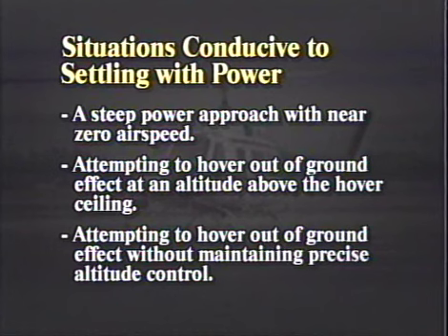Some situations conducive to settling with power include a steep power approach with near zero airspeed, attempting to hover out of ground effect at an altitude above the hover ceiling for that aircraft, or attempting to hover out of ground effect without maintaining precise altitude control.